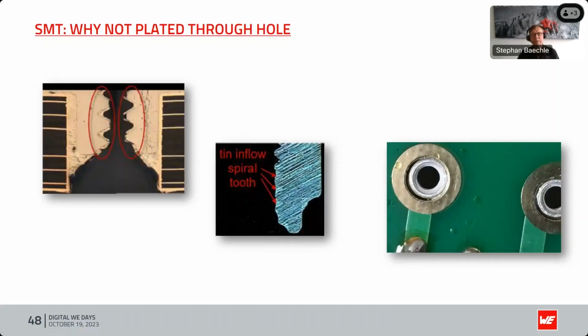Why? When you put the product in the reflow oven, it gets first warm from one side, and from this side the heat is coming, the product is moving, and the product is not centered anymore, as you can see here. And when you have two big PCBs and you want to bring them together with this component, it can lead to some trouble because it's not centered anymore. So please do not plate the through hole.